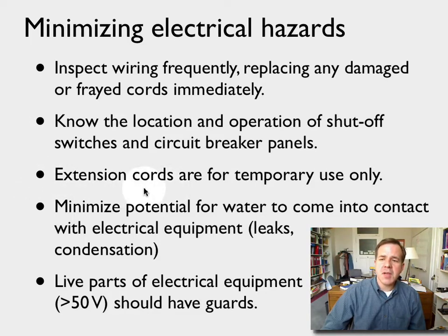Extension cords are for temporary use only, right? So you can plug in an extension cord and use it for a portable piece of equipment. But if you find yourself in a situation where a permanent piece of lab equipment needs to be powered and you have it plugged into an extension cord, then you should really talk with your principal investigator about either moving the equipment to a place where it can be plugged directly into an outlet, or having an outlet placed in a location where the equipment is, so you don't need to use the extension cord.